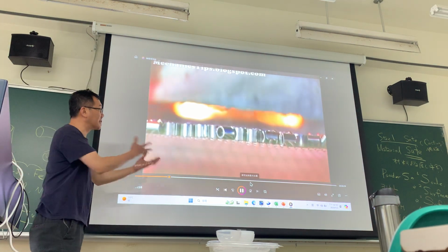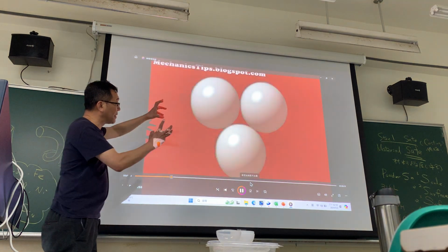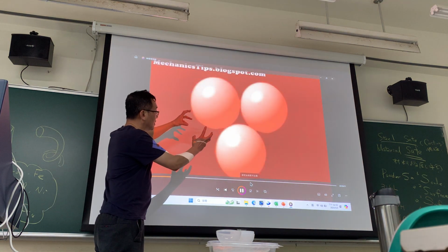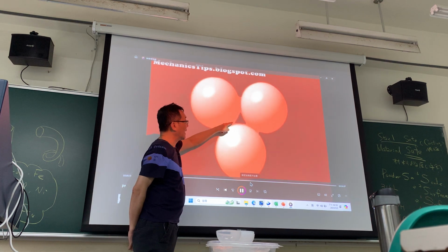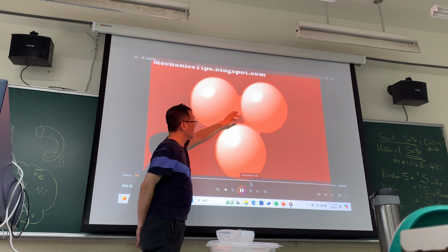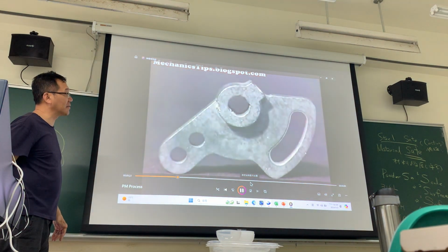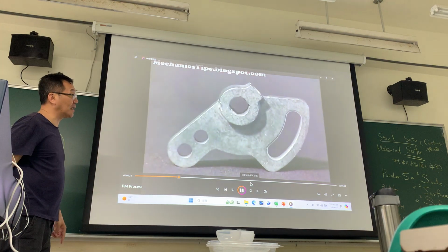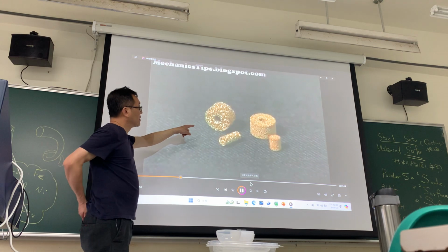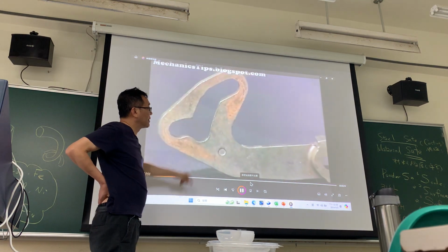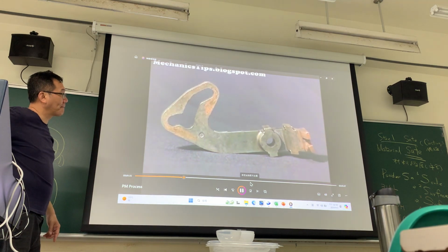So we go to sintering. During sintering, parts are heated at a temperature. Okay, the powder will bond closely. And the shrinkage, so there are fewer holes, increasing strength, because this one is sintered. After sintering, the parts will be strong, although porosity is present. Okay, this can be achieved for certain parts. The performance of structural parts increases directly with increasing density.